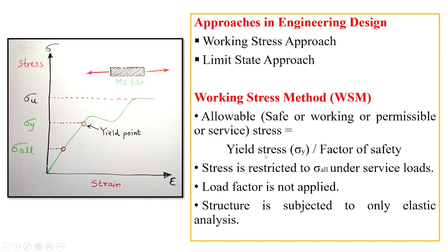That means in working stress method, the stress is restricted to sigma allowable under the service loads or the permissible loads. Here, the load factor is not applied, means the loads are not multiplied with any factor, and therefore the structure is subjected to only elastic analysis.